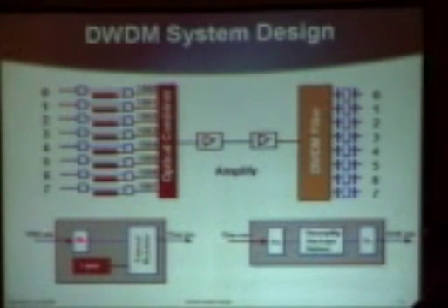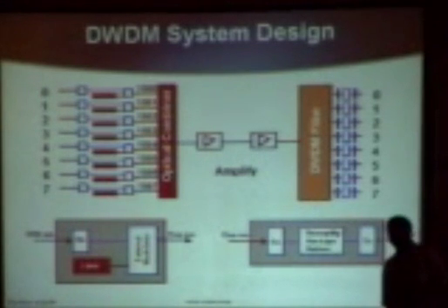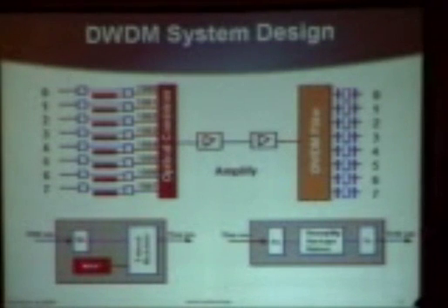That signal is terminated, and it electrically drives generally an external modulator, which means that there is a precise wavelength laser, say 1550 or 1551, that is being driven through the modulator, and the modulation is being applied electrically to that new carrier. So that coming out here is exactly the same electrical signal that went in over here, but it's then converted onto a specific wavelength for multiplexing into the long-haul network.